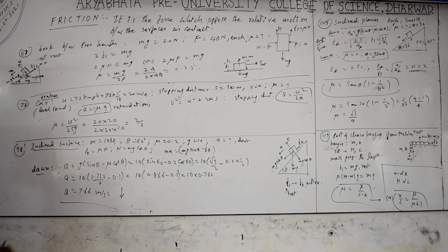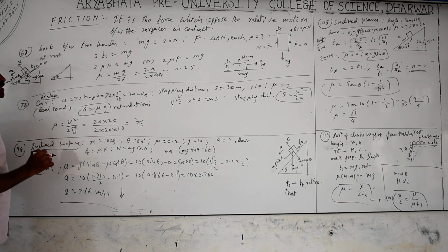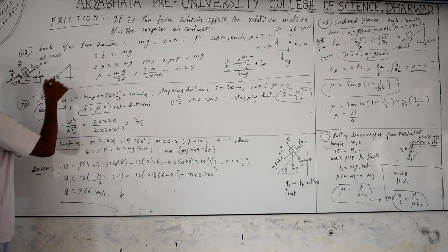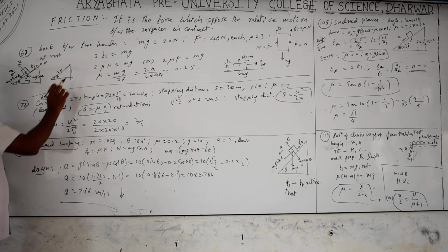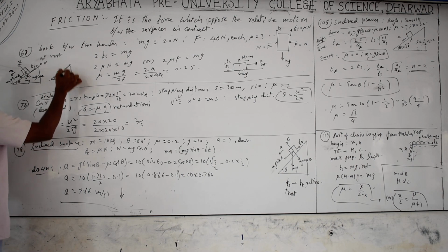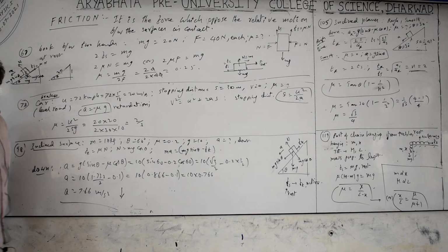And one more point: they will mention slopes like 1 in n, or 1 in 25, like that. For inclined surfaces such as inclined roads or hilly roads, if they mention 1 in 20, it means the height raised is 1 meter when you travel a distance of 20 meters along the inclined surface. That is how inclination is measured.